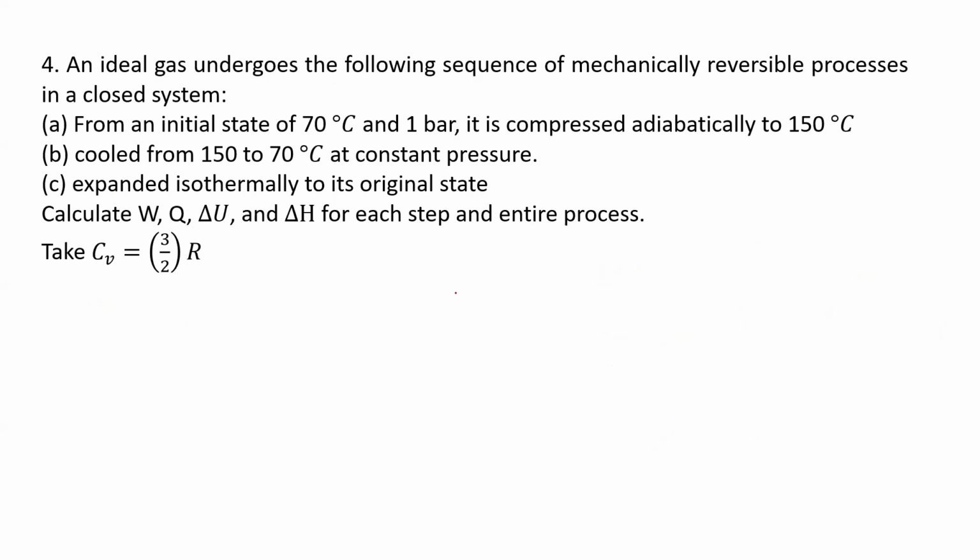Now, in this question, I wanted to include all the different processes we have been talking about. An ideal gas undergoes the following sequence of mechanically reversible processes in a closed system. From the initial state of 70 degrees and 1 bar, it is compressed adiabatically to 150 degrees.